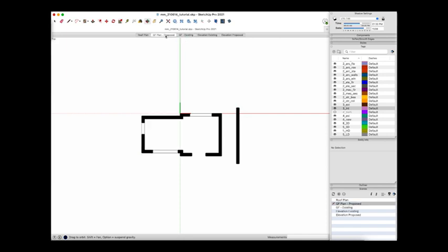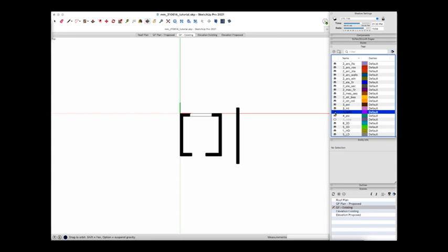Now, how do we do this? It's simply by having part of the component shown under demolition. So there's part of the component which is demolished. Therefore, when I'm showing the existing building, I'm showing both existing, which is this, and demolished, which is that. If I switch from existing to proposed, I'm turning off demolished and turning on new, right? So this is the basic trick.